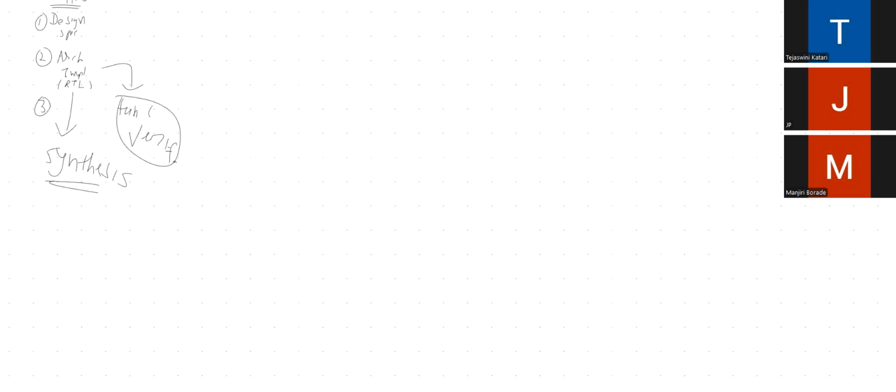See, the synthesis stage is not only converting RTL to netlist. It is the stage where RTL is converted to a technology dependent netlist. RTL will never have any technology dependence. RTL will not get any idea about things like the standard cell area. So the same RTL can be used in multiple technologies, and to convert it with respect to a particular technology, you require synthesis.